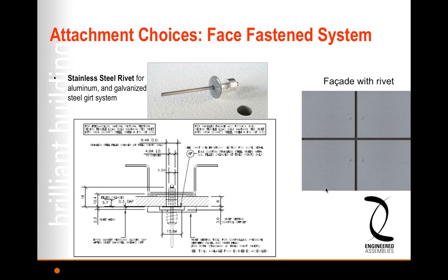This was commented on earlier, and I want to make it clear, we've developed a one rivet system. So it's important in any of these kind of panel products that you allow them to expand and contract. The way that is done is we drill all the holes the same dimension, and the rivets are all the same dimension. And then the two fixed points that are required near the center of the product, this little sleeve is put on this rivet, and that carries the dead weight.